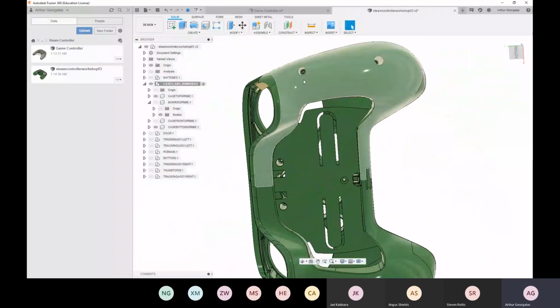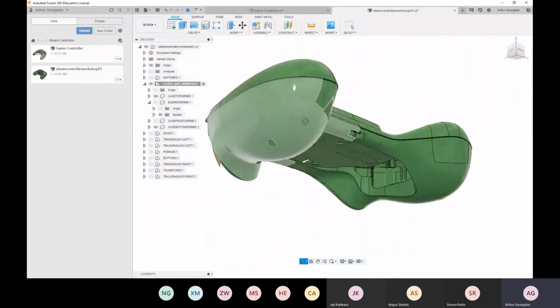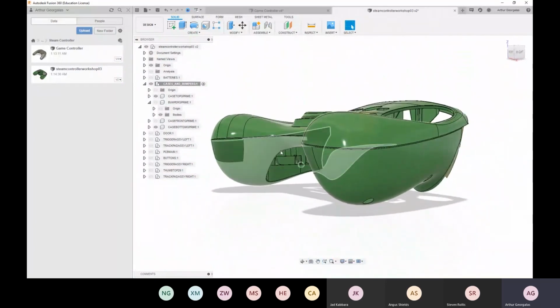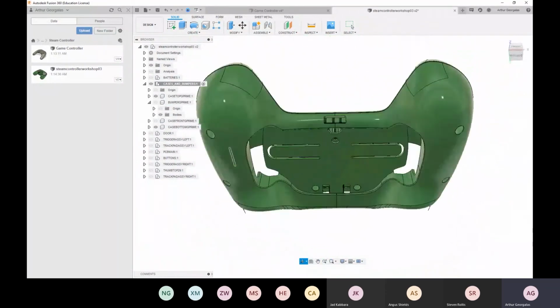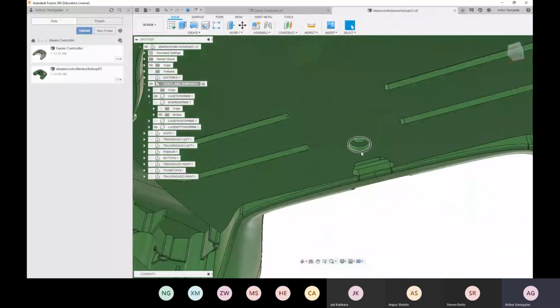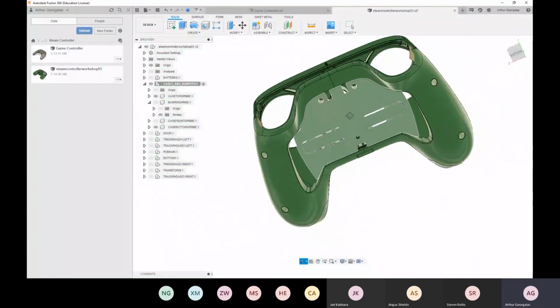Having screws in it is kind of important, and we do want to show that, but to what extent is up to you. Again, if you want to do it really basic and get a credit, you can do just basic screws into solid plastic. If you want to excel and really improve your skills, you'll look at doing proper countersinking that leads to a tighter fit so the thread can actually bite in.